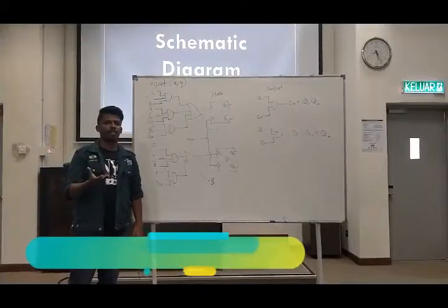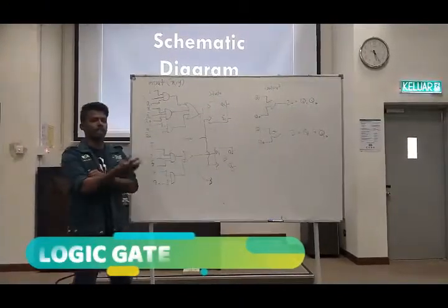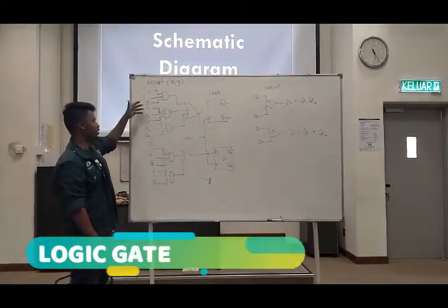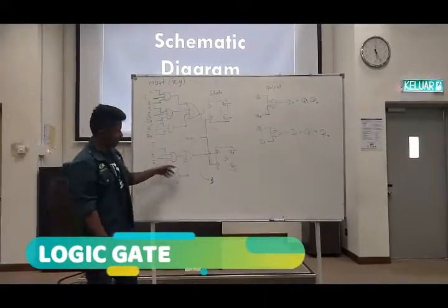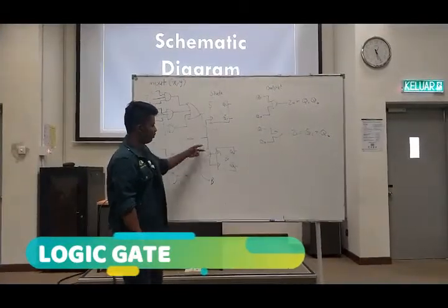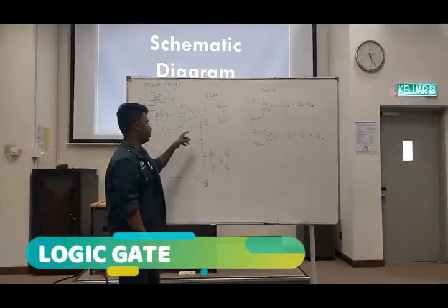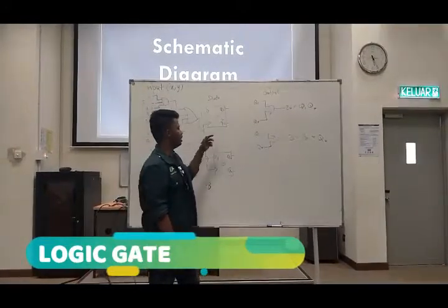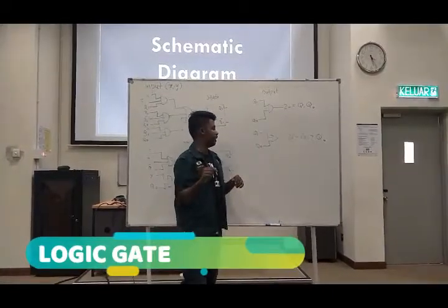Looking at the K-map, what we get is the expression for A, B, and Z0 and Z1. So using the expression, we have designed the logic gate to give an expression where A is equal to something. And this logic gate also gives an expression that is equal to B, and those inputs will enter the D flip-flop, will enter the D, and what we need now is Q0 and Q1. So using Q0 and Q1, we can find Z0 and Z1.